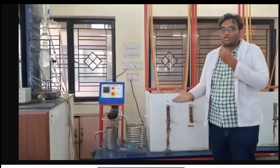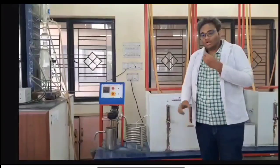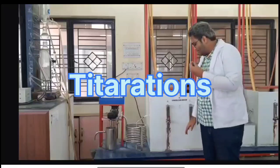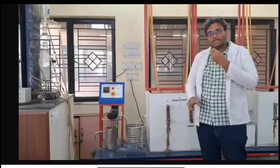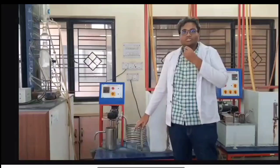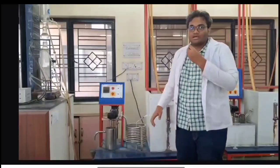We have already seen the standard procedure of titration. Now proceeding towards titration of the CSTR sample. Now that our standard solutions are ready, let's collect the sample from the CSTR and analyze the concentration of reactants. We'll do this using a titration, where a color change indicates the endpoint.